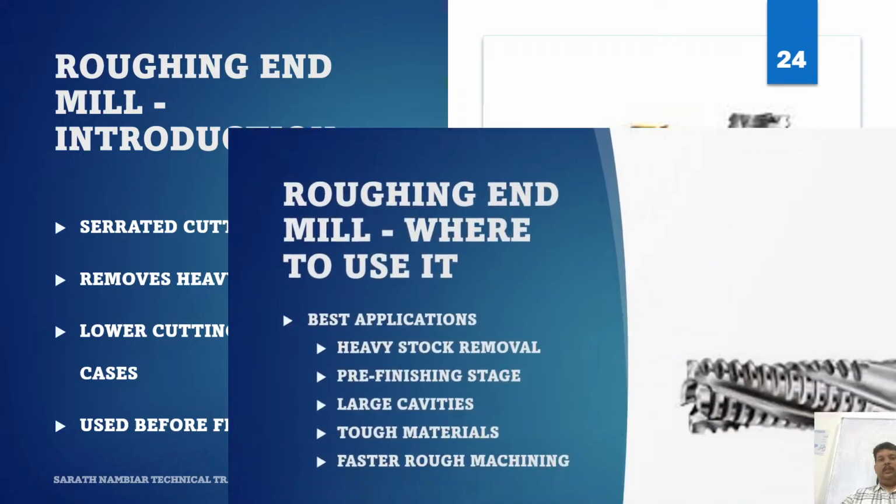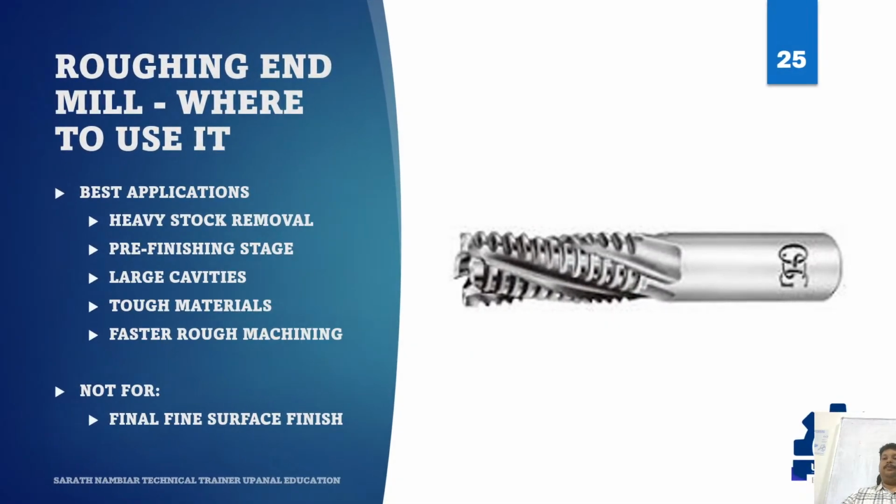Now, the roughing end mill, where will we use it? We use it for heavy stock removal. We use it for large cavities. Then tougher materials where a controlled roughing strategy is required, and we use it for the pre-finishing stage. This means the roughing tool removes most stock, leaving small finishing allowances. Then another tool gives final dimension and finish.